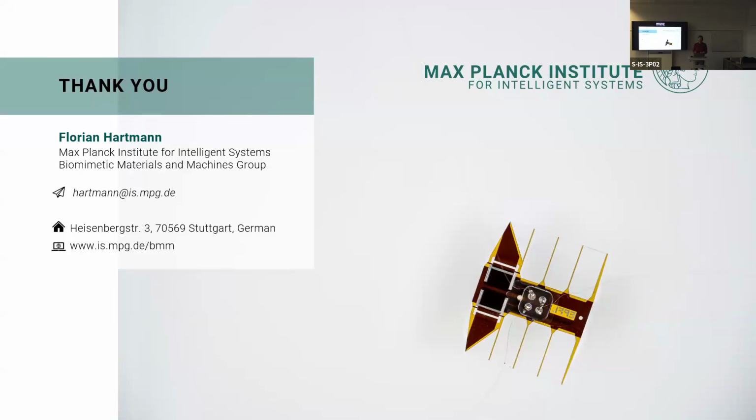While if you use steel for that, you might need much less volume and mass of material, because it's orders of magnitude different. If you want to reach the same forces with a rubber, you need orders of magnitude larger structures. If you don't have the space for these structures, you will not be able to do this with a rubber. And you need to switch to very stiff materials. So therefore, I would say heavy duty work is not possible.